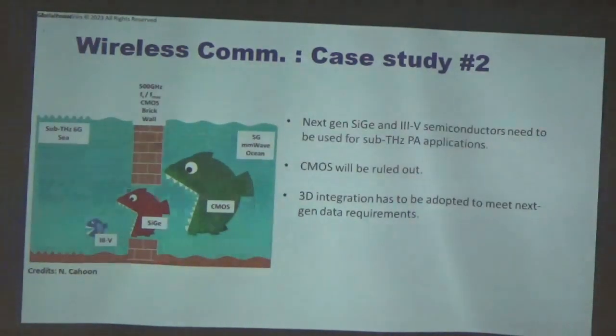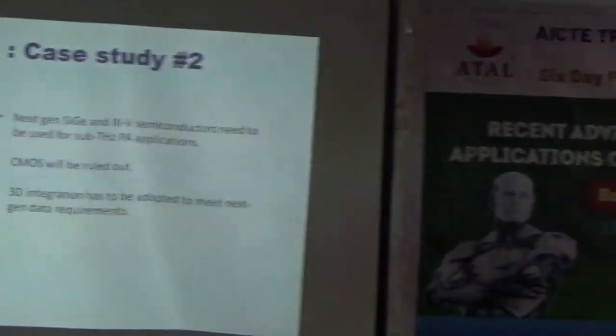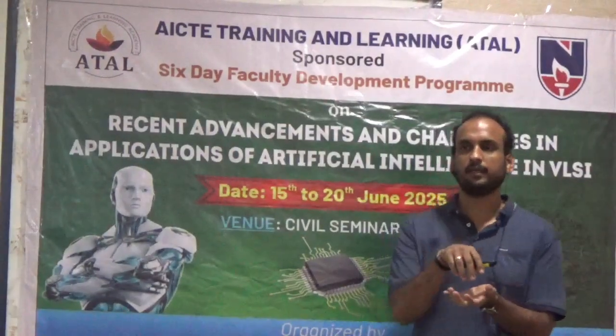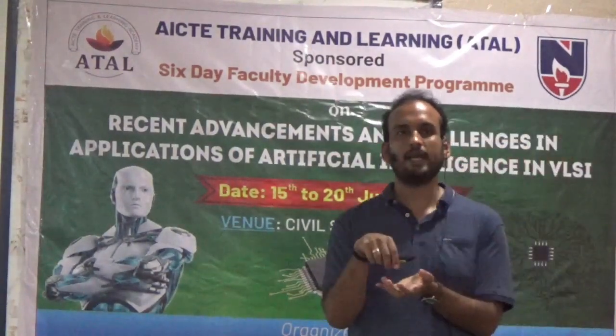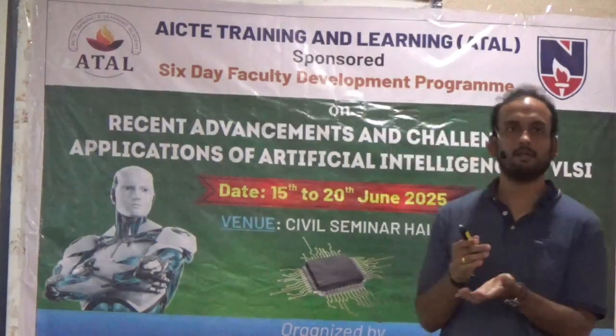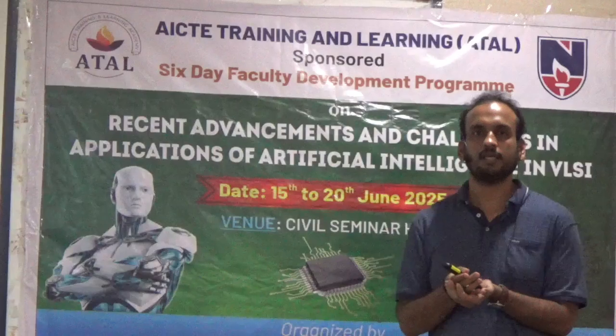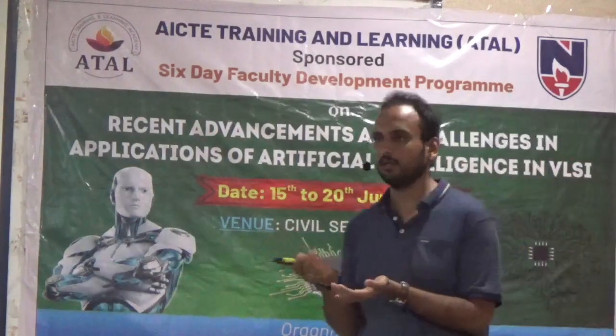So the optimum solution is you design an indium phosphide or gallium nitride PA, and you have different blocks in different CMOS technology, and then use 3D integration techniques. Then interconnect, just put one die on top of the other and do an interconnect between them. This is how the semiconductor industry will go in the next 20 years.